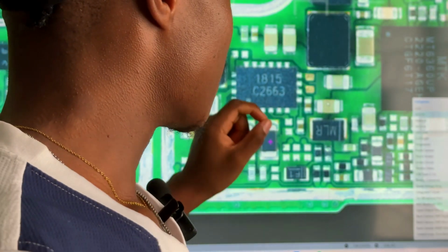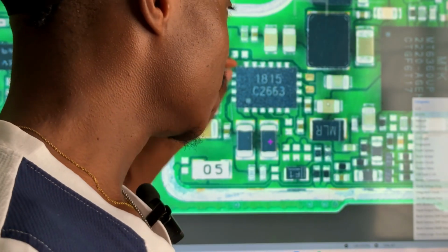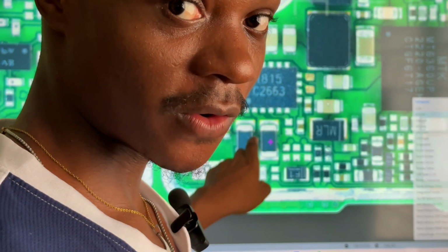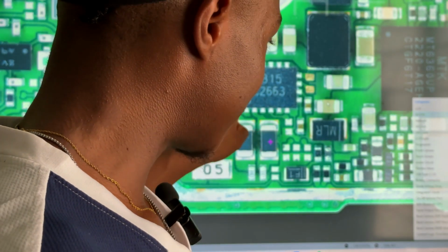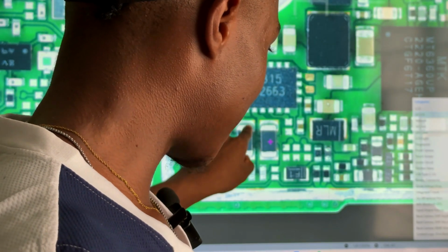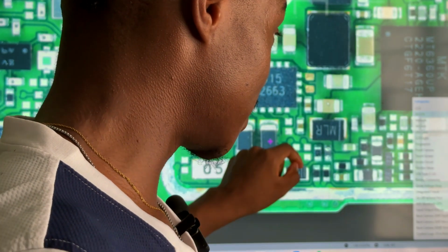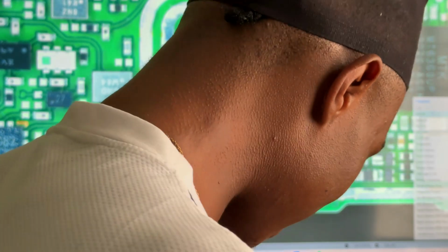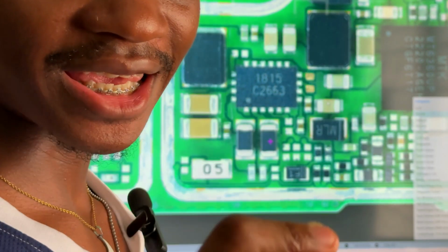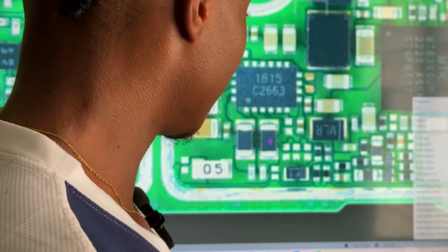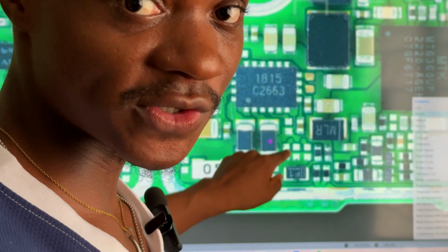You understand? Which means that after checking the connector and the flex, the charging PCB and the speaker, they are all okay. The next thing that you will have to check, these two filter coils, because once the sound leaves the sound IC, one side passes through this coil, the other one passes through this coil, which means that the first thing that you will have to check is if there is any open circuit in these low value resistors or coils or inductors. You understand?